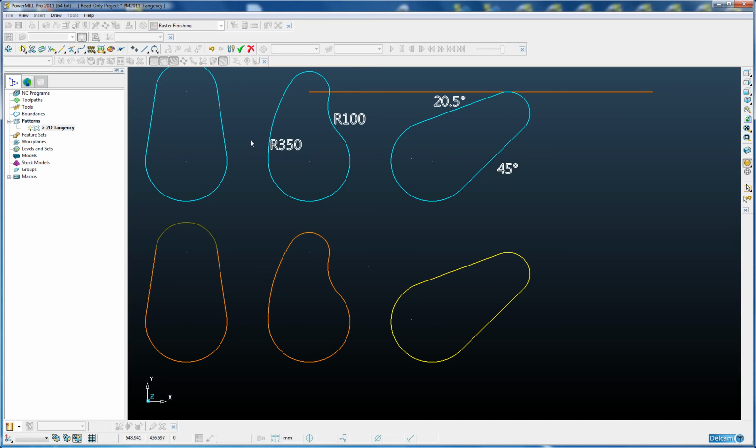Other new functions that have been added to the curve editor are the ability to project curves, either drop, flatten, or embed. These were previously available by right-clicking over the pattern or the boundary in 2010. These now have been added to the curve editor toolbar. And the other new piece of functionality is the multiple transformation.